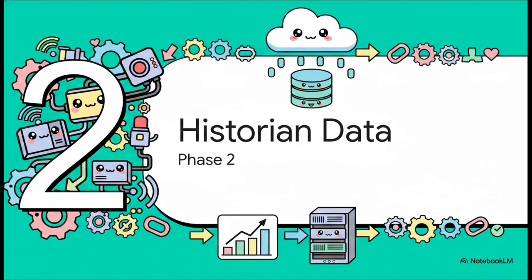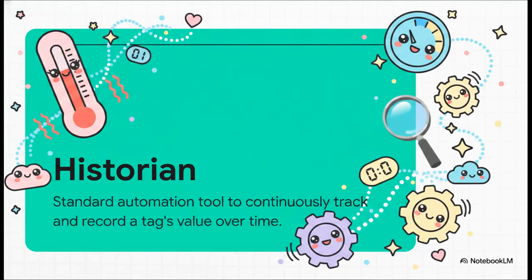Moving right along to Phase 2, historian data tracking. We've got our foundation laid, so let's start moving some data. So what exactly is a historian? Well, it's the absolute standard tool in automation for continuously tracking and recording the value of a tag over time. Think about a temperature sensor reading, or maybe a pressure valve gauge. You don't just want to know what it is right at this exact second. You need to know what it was 10 minutes ago, or yesterday at 3 p.m., right? The historian logs this continuous stream of data for you, effortlessly.